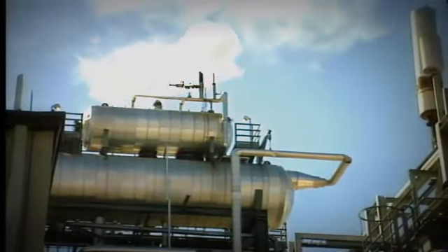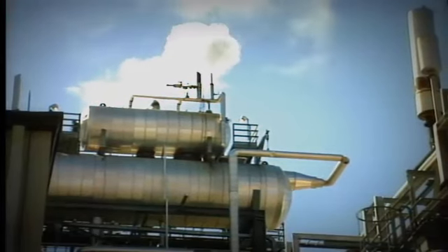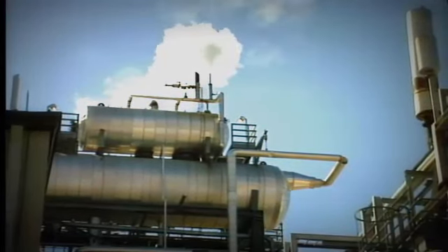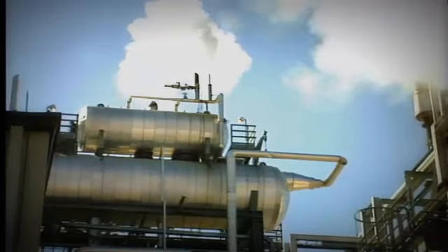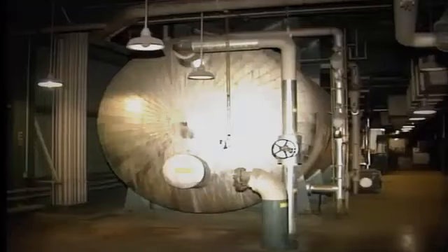In actual fact, the de-aeration takes place in the upper vessel, while the large vessel below is merely a storage tank providing suction to the feedwater pump. In most plants, the capacity of this storage tank is sufficient to keep the feedwater pump going for about 10 minutes, even without receiving condensate from a condensate system. So this should be sufficient for an emergency shutdown.